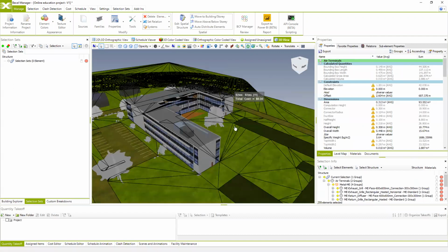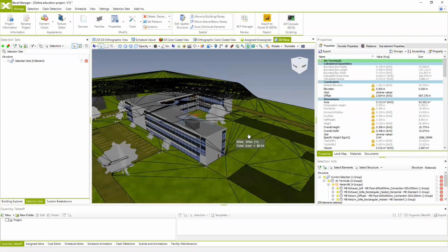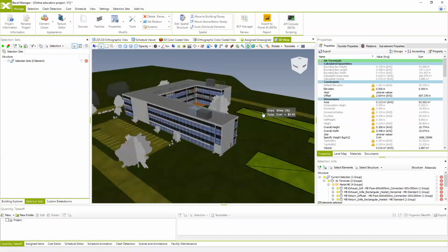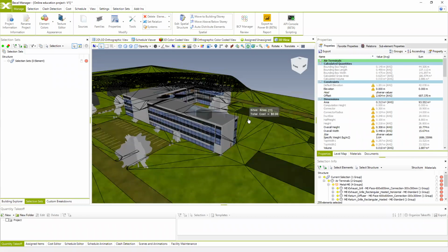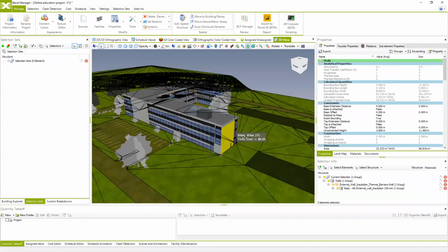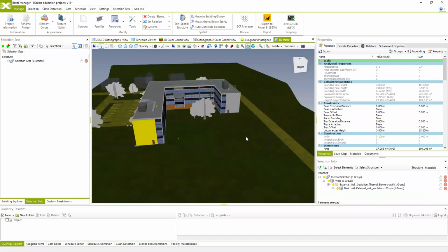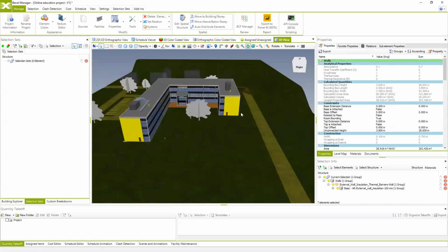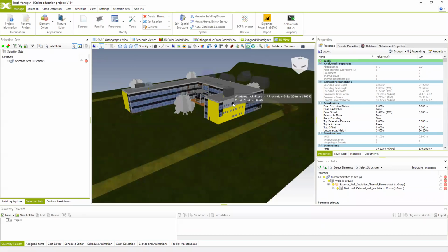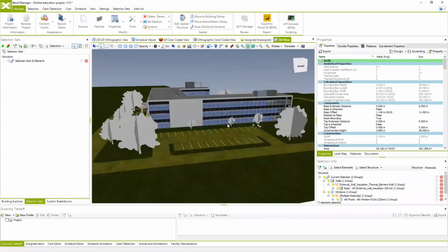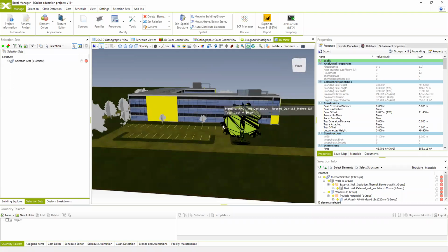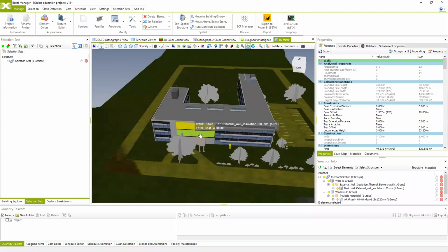But before that, let me explain how you can manually create groups, though there are a lot of flaws why you should not do that manually: every time you update the BIM model, you have to repeat the same process, manually selecting specific BIM model elements and adding them to or removing them from specific groups. So let me show you how this works. I'm going to manually select specific BIM model elements from the building. These are some facade walls. Let's say this is it.